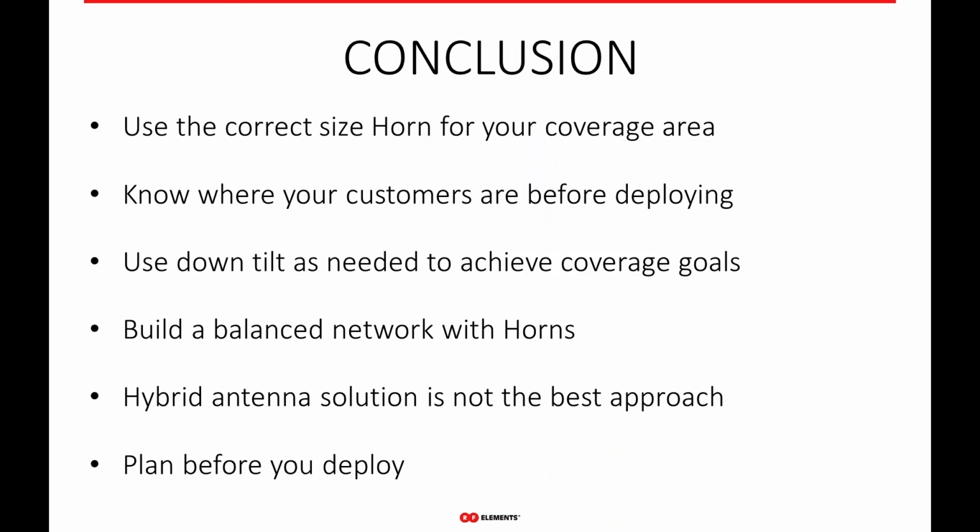So as we think about all those different methodologies and different ways of utilizing horns, we can look at the conclusion of all these different methodologies. Using the correct size horn for your coverage area, again, is very important. Everybody always kind of wants to run to the highest gain. This is kind of an old way of thinking, and it's based on your experience because of the antennas that have been available and used in this industry for such a long time. Really, it's not really necessary. So using the right size horn for your coverage area is really important.